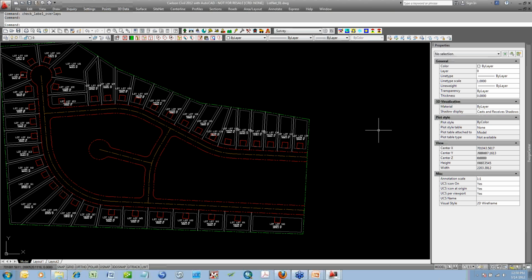Okay, basically she was using the renumber tool to go ahead and do that. It's not an automatic tool. What you would do is basically, as she was showing on the screen, you would indicate what number you wanted to start from. In that case, if you wanted to redo from 1 to 100, start with number 1, and then just use that fence tool to indicate what order those lots would go in. So it's not a one-click reverse tool, but something like that.